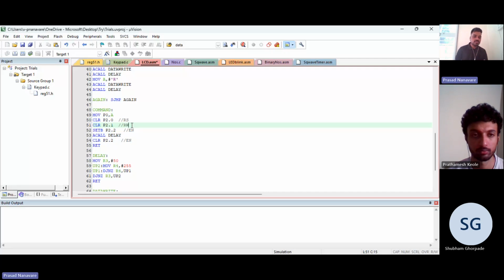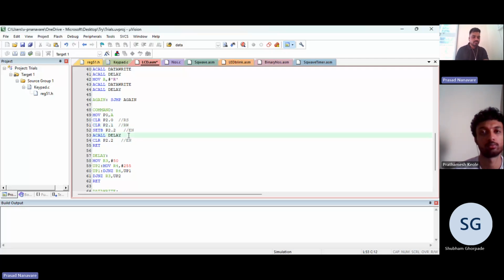When it is 4-bit, we'll have to write another function wherein we are checking a busy flag, and for that we are reading something from the LCD, right? That's why we need to put it in read mode then. Not right now, but when we are actually doing it, like the 4-bit coding with busy flag. Even 8-bit can be done with busy flag, but the last bit of the data pins will be considered as the busy flag bit. So that comes in a slightly different format.